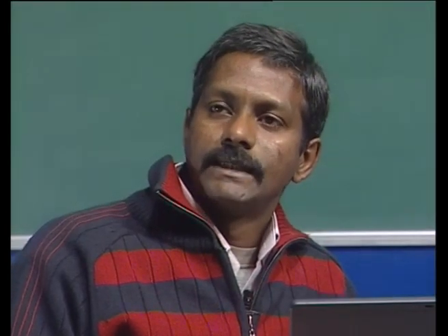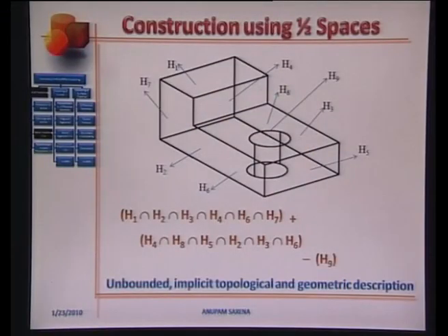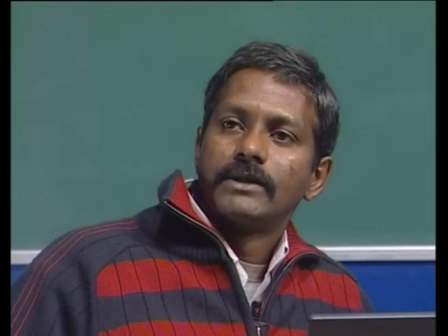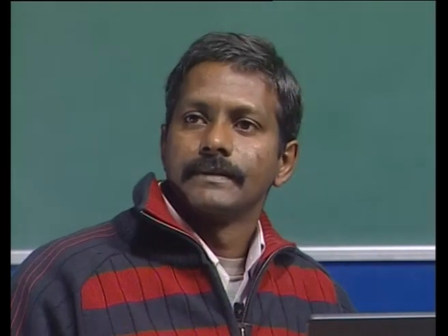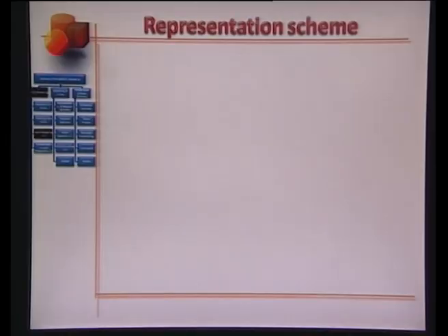A few disadvantages of this concept are that the half spaces can be unbounded, and these set operations would only implicitly store the topological and geometric description of a solid. Data storage would not be explicit. There are other alternative representation techniques which are used. We'll look at them. But first, what is expected from a representation scheme?